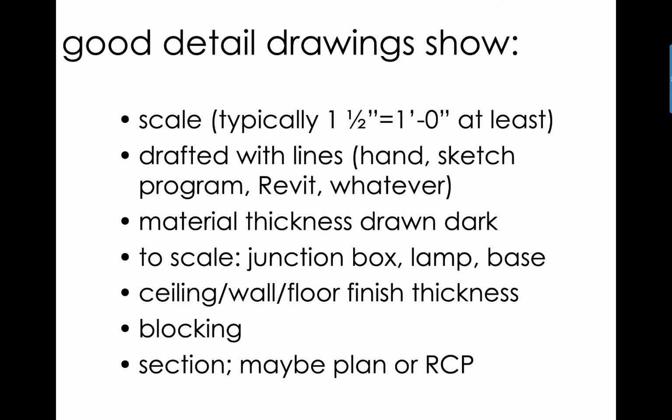So the detail drawings that I'm hoping you will draw will obviously be to scale. These are construction-type drawings. Usually we draft them with lines in Revit, because in Revit you don't model this level of detail. So when you've come up with a design and created it, you're going to draw a section. The section will basically be detail lines, just because there's no way to model all the bits and pieces in Revit. Or there is, but you'll spend the rest of your life doing it.